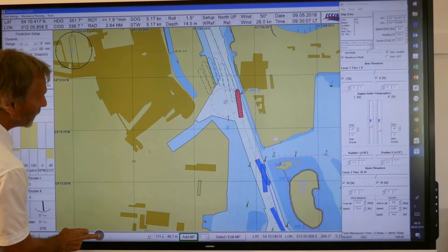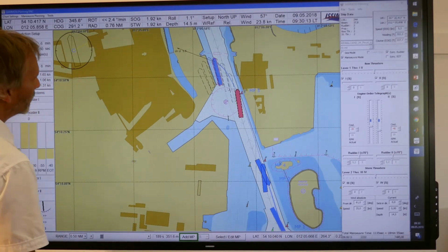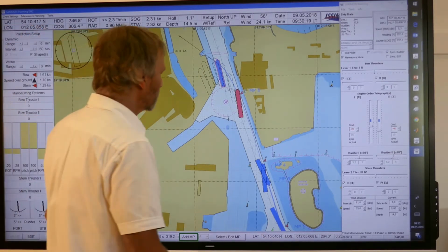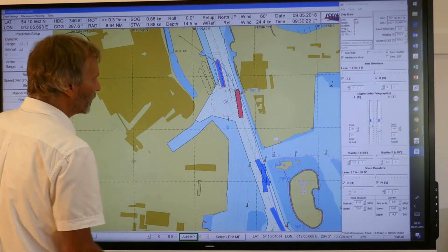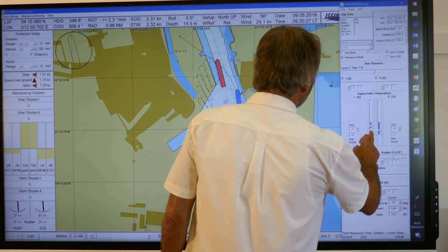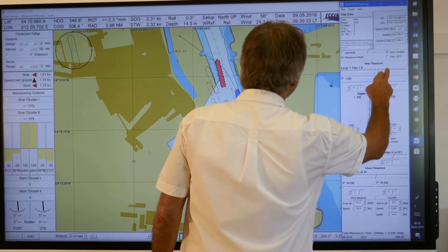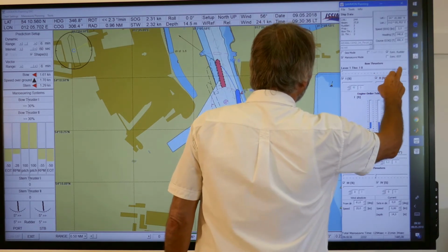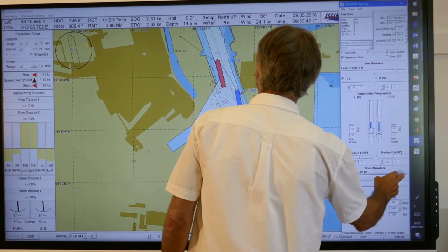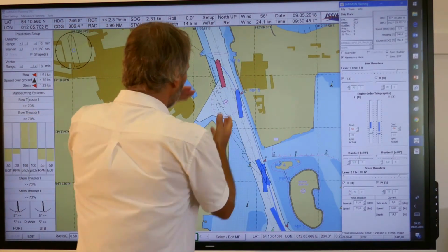So the final concept would be to go here, then and to use all maybe up to here. This could be a strong point for maneuver. We still have 2 knots, but here we can really stop her more consistently. We work with the thrusters against the wind, with both thrusters, and then you see that we can stop her dead in the water up to this position.